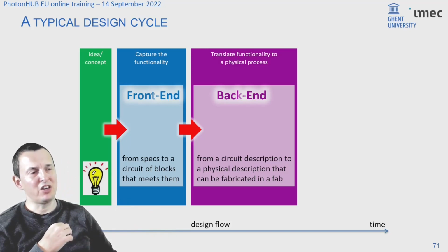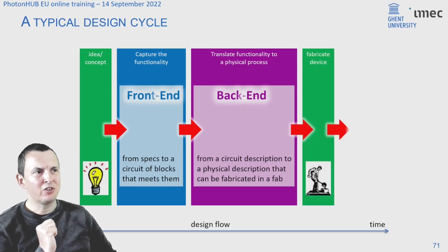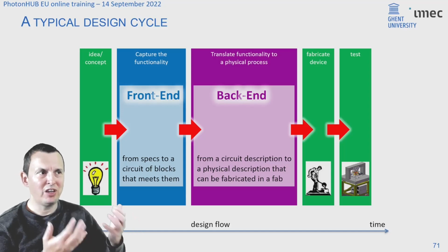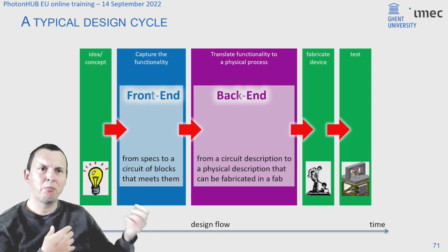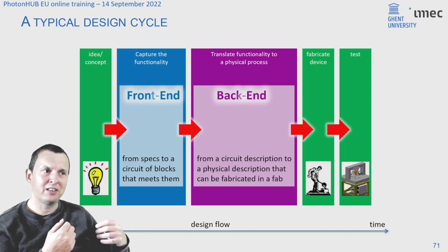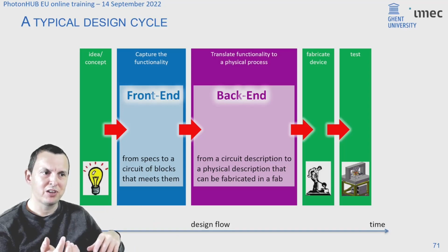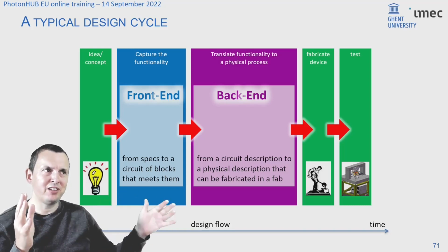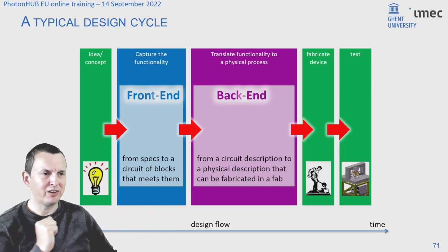Now, essentially, okay, if you end up with a design that needs to be fabricated, you're done, right? Well, not quite, because you cannot fully decouple the design cycle from the actual fabrication process. So you need to be aware of the fabrication process, and at the end, your chip is going to come back, and you need to test it. And so you need to take that testing and the requirements for testing already into account during your design process. So I typically consider the fabrication process and the test actually as essential to your entire design cycle.